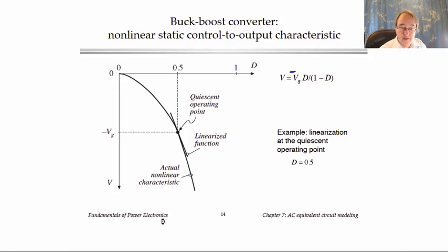So you might then try to do a similar thing. We could say operate the converter with a quiescent duty cycle or steady state value of 1/2, which from solving this expression tells us that we'll have a resulting quiescent output voltage of minus VG. And then on top of that, we could say, what if we also added some small variation, d hat, in the duty cycle?